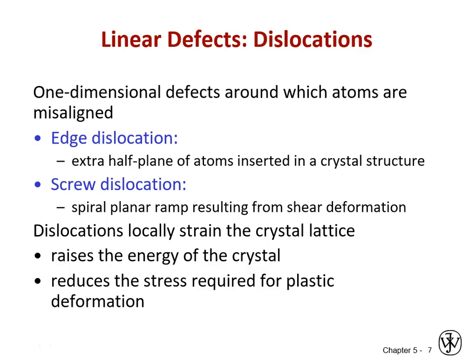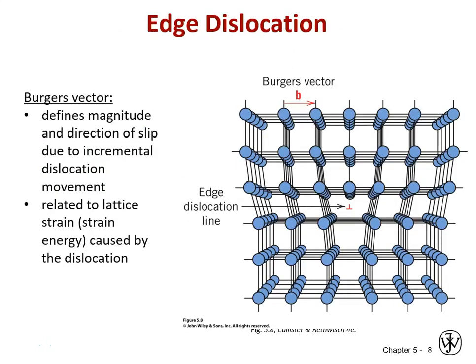The area around the edges of these linear defects, the surrounding atoms are not in their equilibrium positions, and so the energy of the crystal in that local area is a little bit higher, and that has the impact of reducing the stress required for plastic deformation quite significantly.